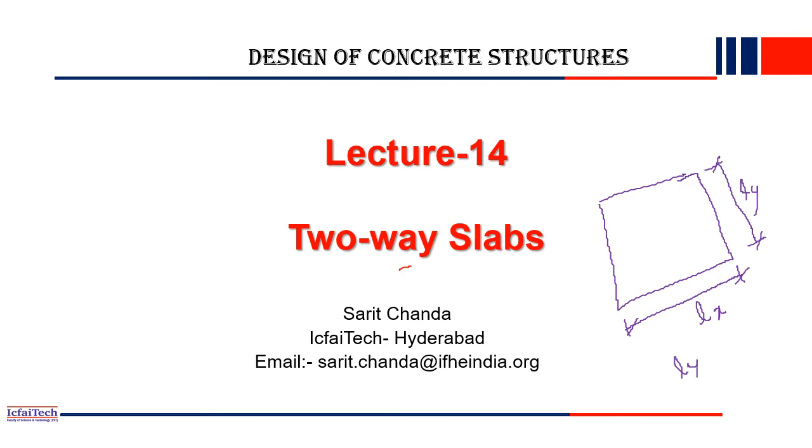So if Ly by Lx, the ratio of the two dimensions, is greater than 2, then we call it a one-way slab. So based on the ratio of the two sides, it may be either a one-way or a two-way slab. If Ly by Lx is more than 2, then it is a one-way slab, and if Ly by Lx is less than or equal to 2, we call it a two-way slab.